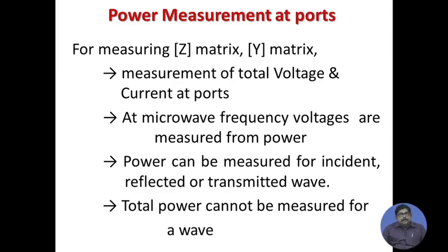As voltage is measured from power, voltage also cannot be measured as total at microwave frequency. At low frequency it can be done, but at microwave frequency there is no point talking about total voltage or total current.